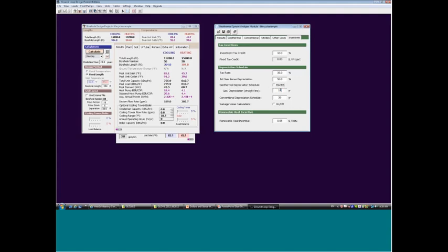You can define the straight line depreciation for a geothermal system. And then we have our conventional depreciation schedule. Conventional HVAC equipment has a 39-year straight line depreciation. We've listed that there. You can choose your salvage value, whether to include it in the calculation. Again, the main benefit of that really is if you've installed a $1 million loop field 20 years in the future, what's the value of that loop field in the ground? This is a way for you to estimate that. It does have a significant impact on the life cycle analysis.